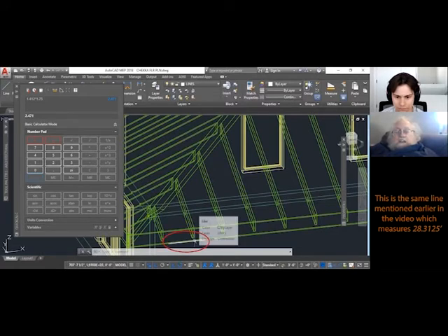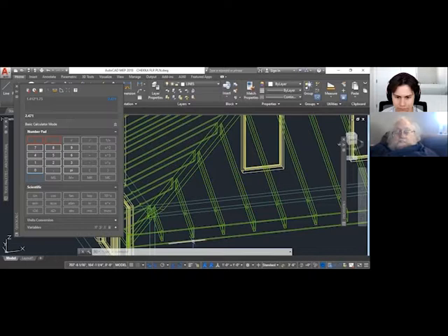My first jack, I measured this length. I have to subtract 2.47 inches from that, and then that distance that I ended up with, from the point where that edge of the hip intersected the wall to that joist, is the same distance my jack rafter is going to travel horizontally this way.